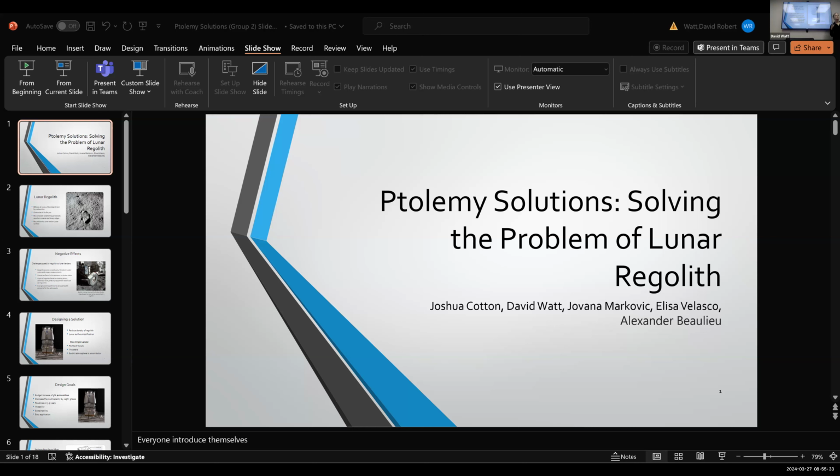This comes from the fact that we know that the Blue Moon lander is transported using the Glenn rocket, which is 7 meters in diameter, but the Blue Moon lander is 5 meters in diameter. So we didn't want them combined to take up more than 1 meter in diameter, so both of them are 0.44 meters in diameter. We had the most leeway with our height, and we ended up using a height of 0.92 meters. We calculated this based off of how big the tarp was and how much room we would need to fit it inside of the capsule. And it's just showing the entire structure by itself.